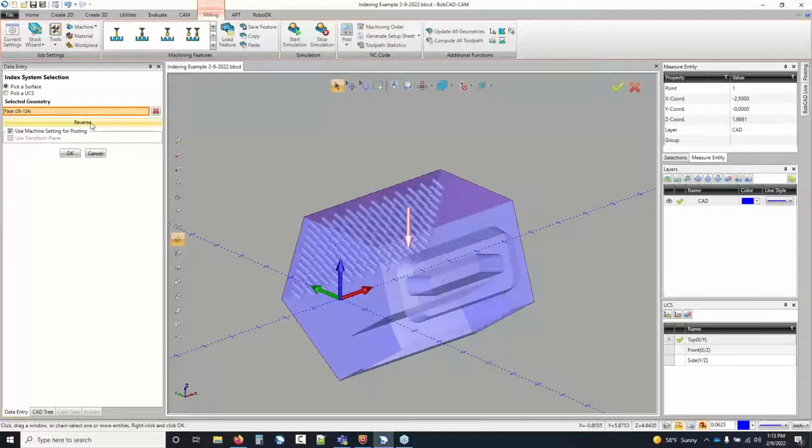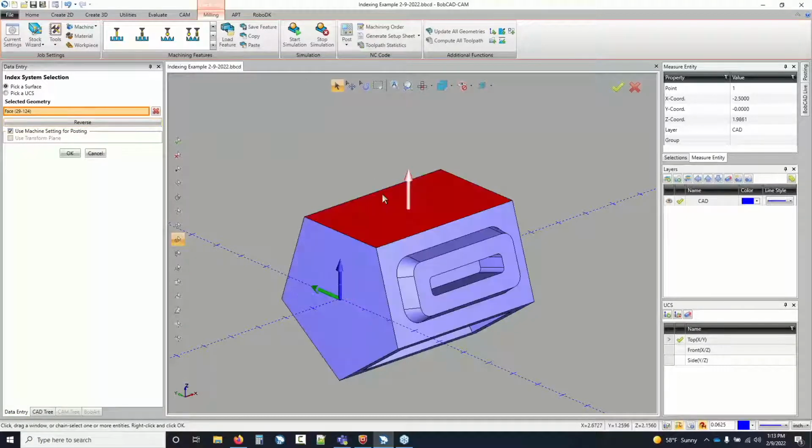So you always want your arrow to be perpendicular to your part and usually facing the outside. You're usually going to have that arrow pointing away from the center of rotation. Because again, if you get that wrong, your tool is going to think it's coming from the opposite side of the geometry, and it gives you just a real hard time.